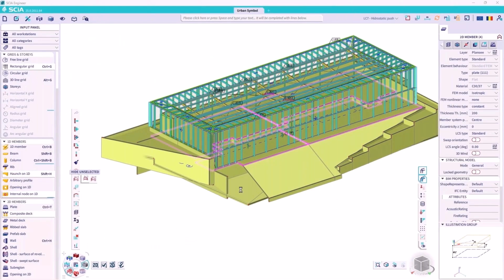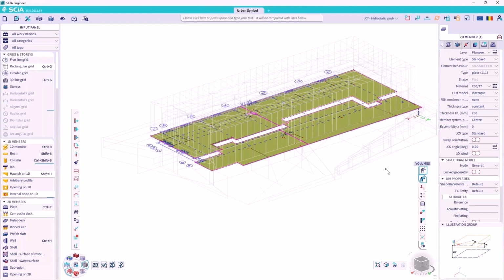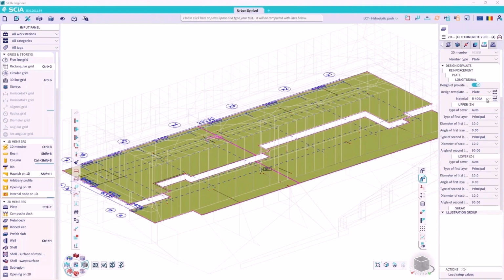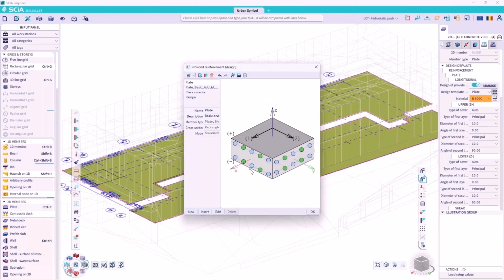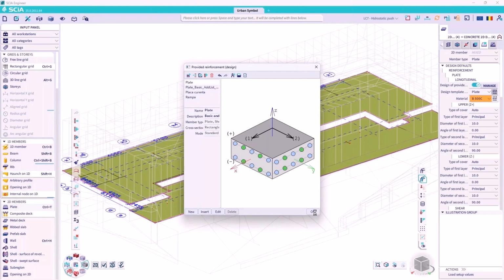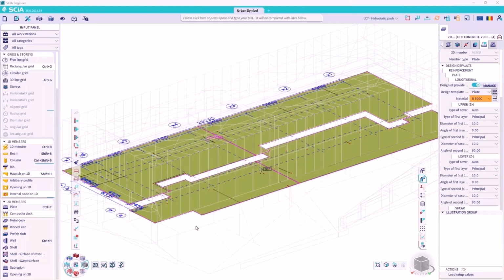So we can isolate these two slabs. There's also a joint that we inherited from the underground parking. We can look at the slabs, and we define some templates, like we choose the quality of reinforcement steel and a recipe. So what you see in blue is the typical main reinforcement, and with green, we give it the possibility of adding additional reinforcement exactly where it's required.